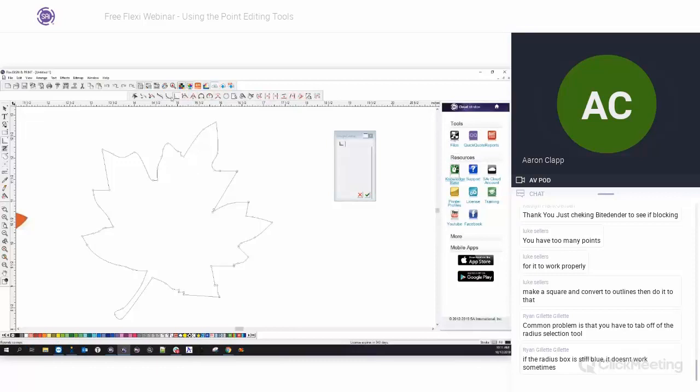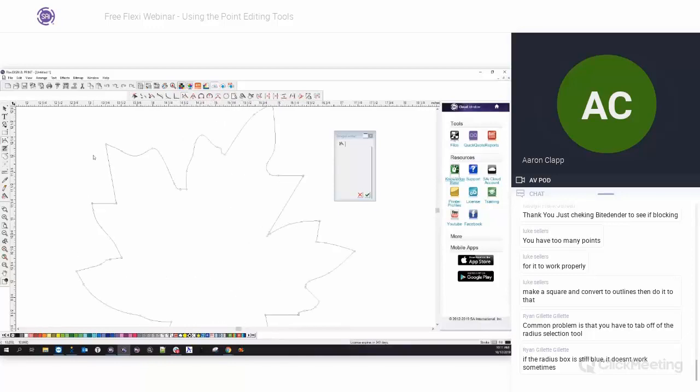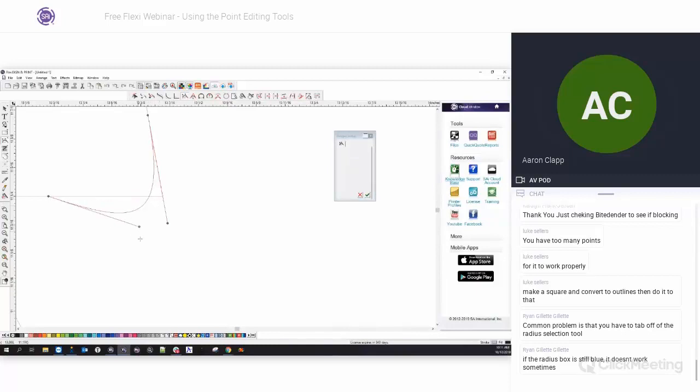The next couple ones here are going to be related to arcs. These are 3 different methods of creating an arc. So let's zoom in on a sharp corner here. This sharp corner looks adequate to me. So I'm going to click on here, and I'm going to click on this corner. This particular style gives me Bezier handles that I can grab onto. And so now I can modify these based off of these Bezier handles. That's the unique feature about this particular one. And I can drag these points around, make it a little bit wider if I need to, and move these things.